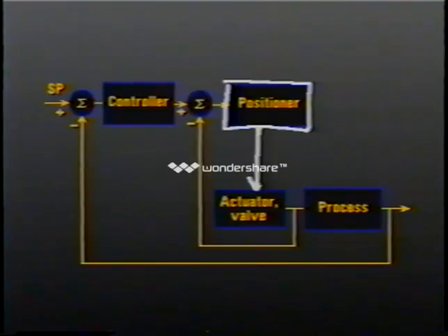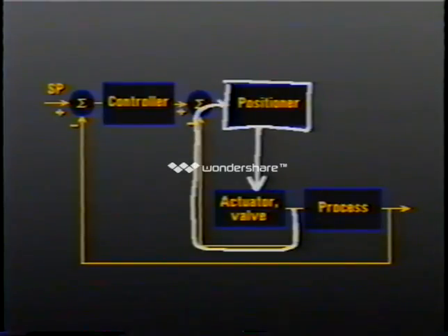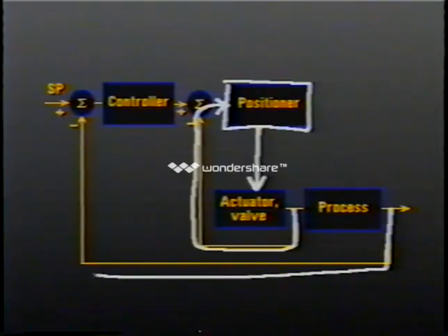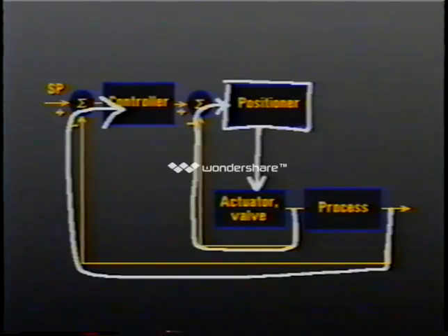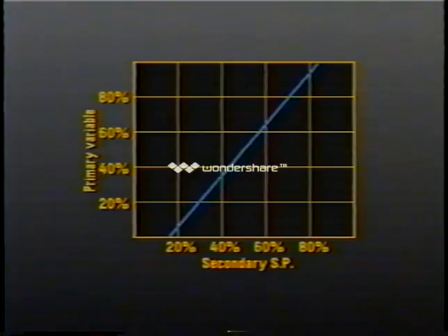control valve to move. The movement of the control valve provides feedback which indicates the actual position of the actuator, which is the process variable, to the positioner. The valve and its positioner, therefore, become the secondary loop in a cascade system. Again, notice that the primary loop must be slow in order to use a positioner. Otherwise, its effectiveness will not be realized.